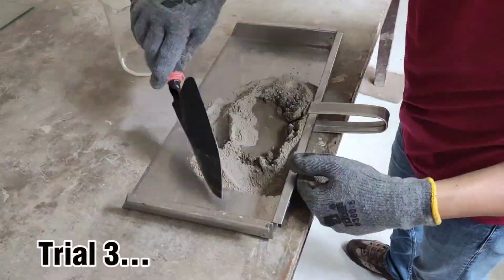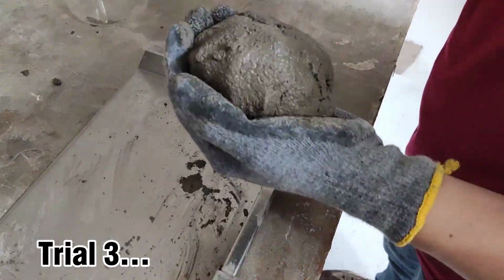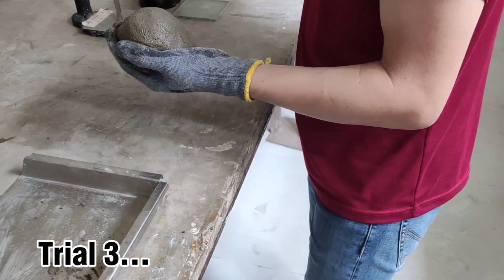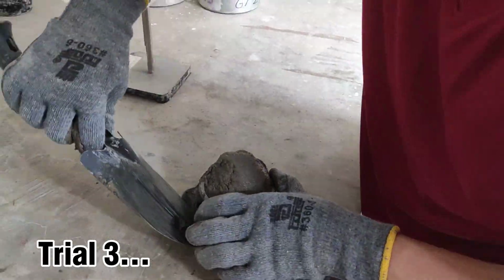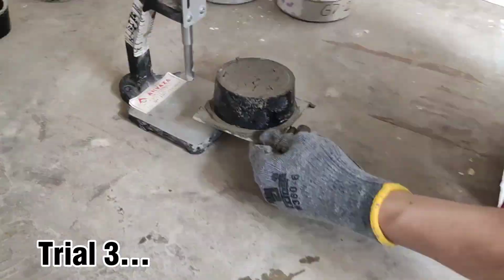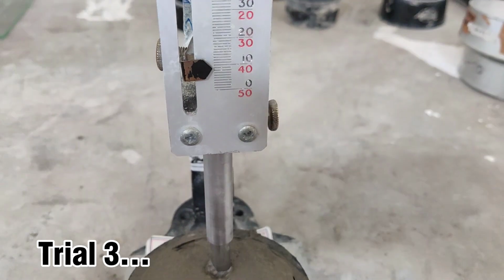And lastly, finally, we used 175 milliliters or 35% of water for the third sample. We finally got a penetration of 7 millimeters, which is within the acceptable range for normal consistency.